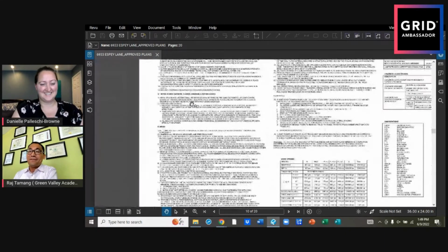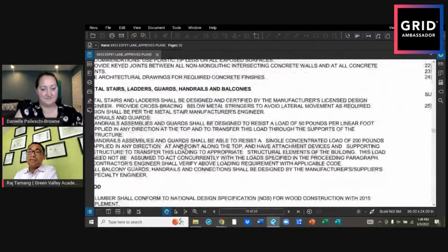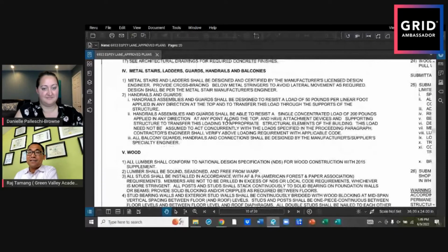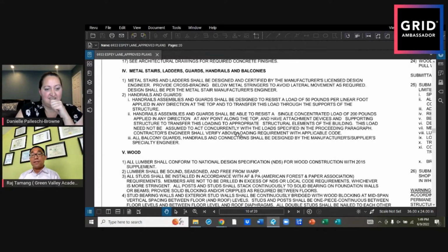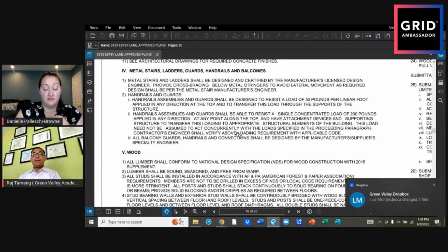Even in concrete, there's so much to talk about, not just how the concrete gets to strength. What is the process of getting the strength? What can you do to control it? That's why, before I forget, in a commercial project, if you pour concrete in hot weather, you'll see they're actually spraying water. Exactly, because you pour the concrete and it's so hot outside that it dries so quickly.